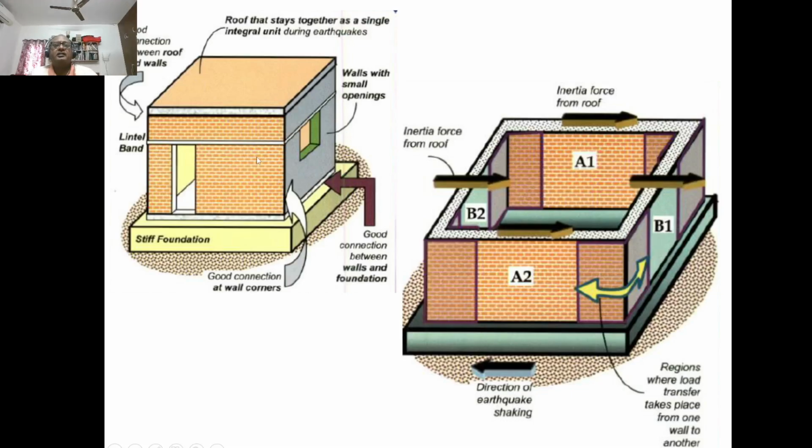And of course, the normal way of taking care in such a masonry structure is, you will have a lintel beam here throughout the structural system. Suppose you have a lintel beam here, that will become a tie everywhere, and the action is slightly integrated, and that is slightly better. So that is the way it is.